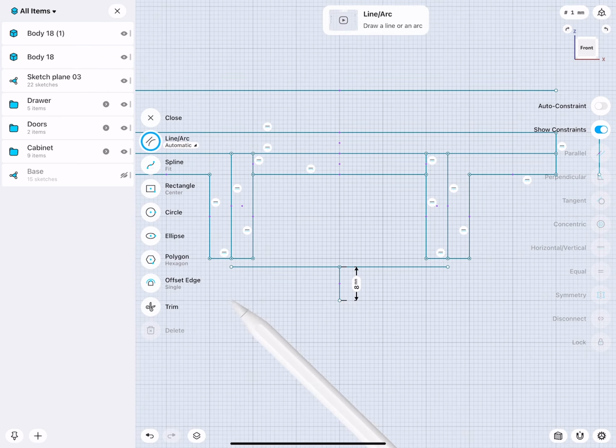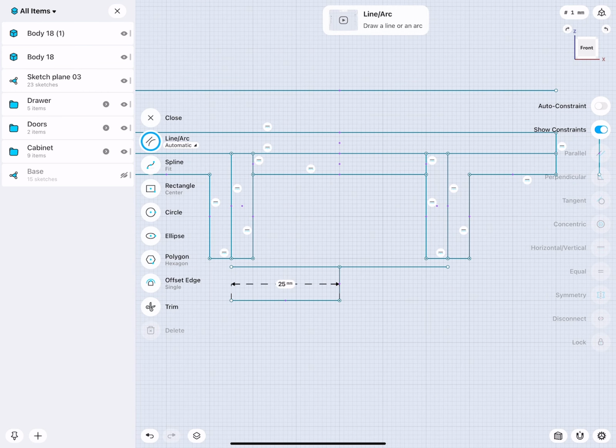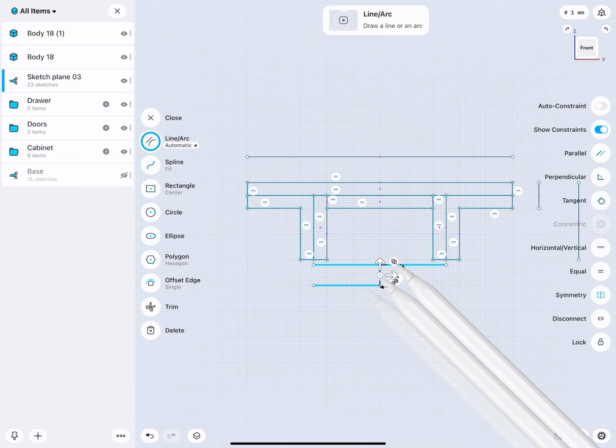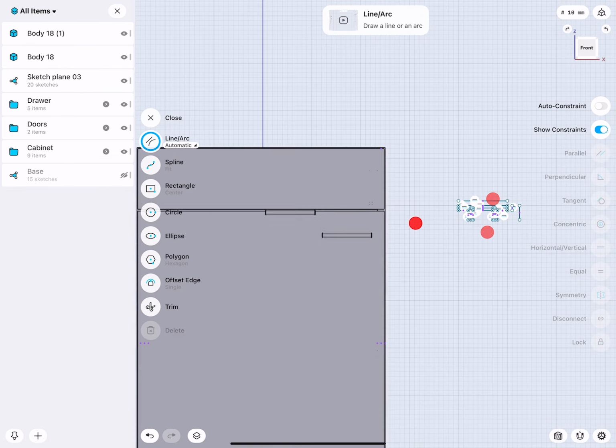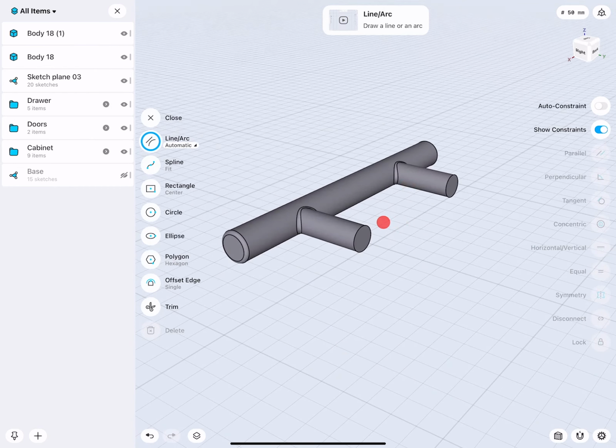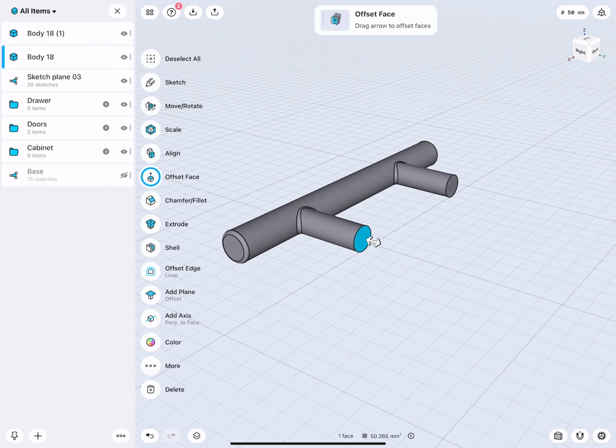Okay, so this means this is 25. Okay, so that means if I take 1 point, align it to the center of the drawer face, I have to move it either left or right by 25 millimeters. Okay. Just a simple demonstration how you can find calculations or do calculations simply via geometry.